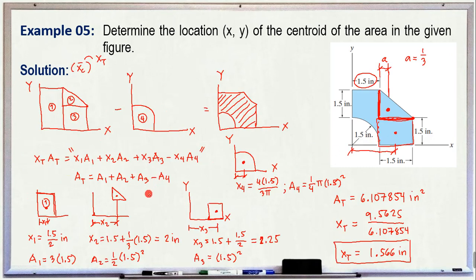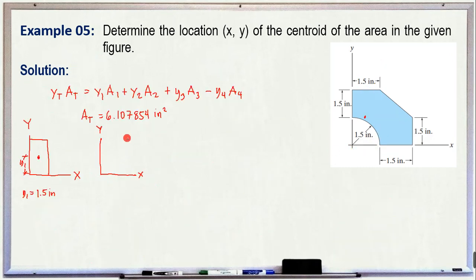so we have, from the previous slide, the triangle. The location of the triangle is right here. This is its centroid, this is our y2. If we draw hidden lines here, here is the centroid. So this one right here, let's say, A, and A is just, since our reference here is the base, not the vertex, 1/3 of the height of this triangle.